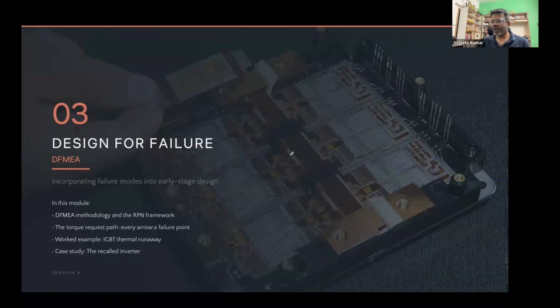So, one of the most important activities that you would do engineering for an OEM is design failure mode effect analysis, right? The failure mode and its effect, you would go ahead and analyze it. And when are you analyzing it? You're doing it at design stage. So before you even have started implementing it into hardware, you'll do a DFMEA.